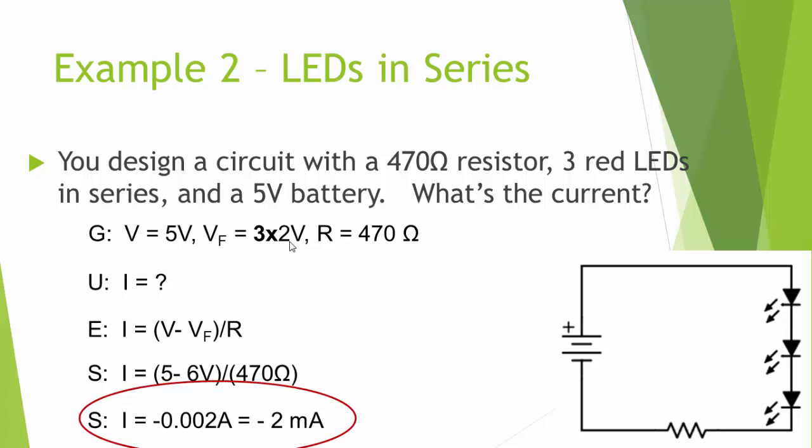So we need to keep in mind that anytime the forward voltage drop exceeds the potential available from the potential source, we'll see zero current. So this is in fact the answer to what's the current on this question: 0 amps. And you should be able to produce this on a test or quiz.